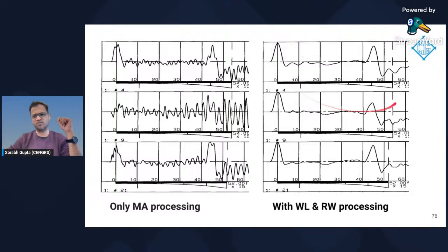You get a solid head response, a solid toe response. Your pile lengths are consistent, and this is the key: when you carry out several tests on the same pile, your PIT data must be almost identical. And this is what we are getting. So, good pile, no problem. We can pass this pile. We can go ahead without any problems.